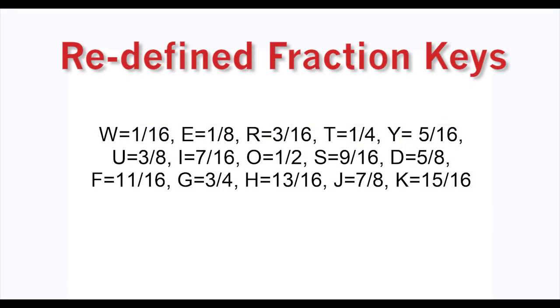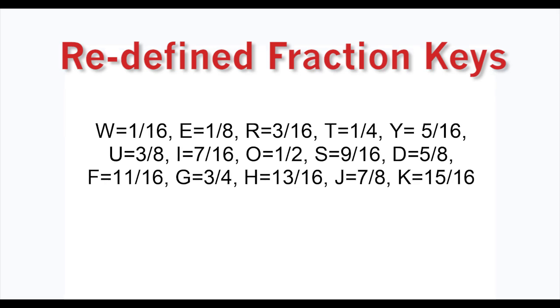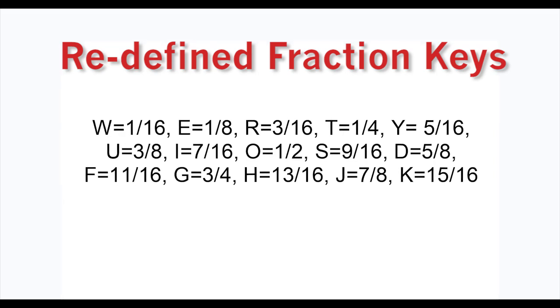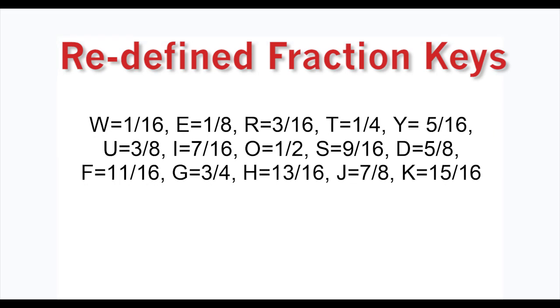We use what we call redefined fraction keys to enter fractions within the inventory system, whether it be in the description of an angle or plate, or a fraction that you're using for the length or width. For instance, for the 1/2 inch fraction, you just press the letter O. For the 9/16 fraction, you just press the letter S. So you don't have to type in whole fractions or the decimal equivalent or whatever.